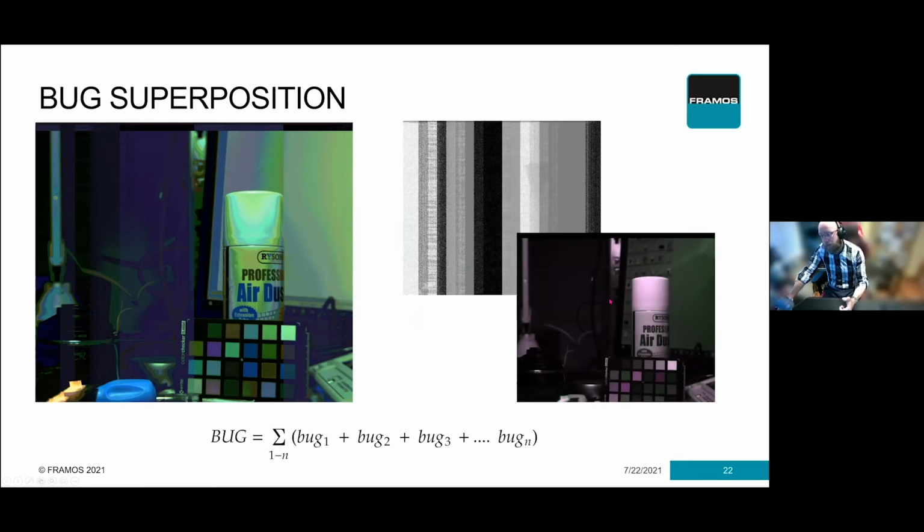And we have, shall I say, the FPGA has an incorrect configuration of which is the correct start pixel. So when we combine these two, we actually have both vertical noise, we have noise where there shouldn't be any. So in this vertical part here, this is where your optical black would be, and it should be dark. So we have all these weird symptoms. We have this posterization. It's actually hard to see that this is both a color error and just corrupted data. And so if we take a little bit of time to look at this, it definitely pays to be suspicious that there's more than one thing going on.